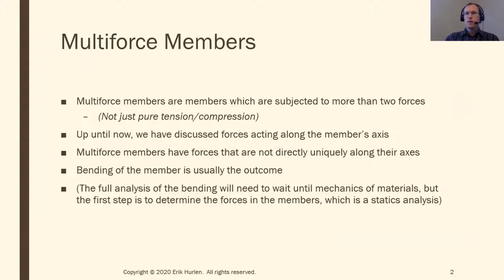So any member that's not in pure tension or pure compression is called a multi-force member. So it can have some component of force acting perpendicular to its axis. So not just pure tension or compression. Usually when this happens, the member is going to be bent a little bit. So if I have a member and I push it right in the middle, it's going to end up bending that member. The amount of bending is not important yet.